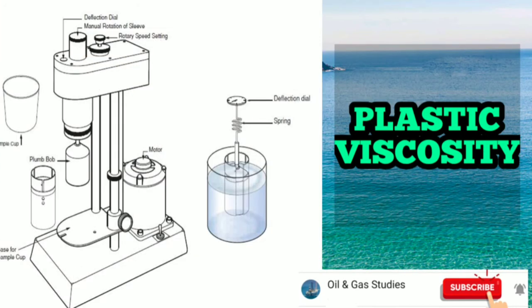Third is plastic viscosity, PV. Apparatus: viscometer or rheometer is a device used to measure the viscosity and yield point of mud. A sample of mud is placed in a slurry cup and rotation of a sleeve in the mud gives readings which can be mathematically converted into plastic viscosity and yield point. Multi-speed rheometers are recommended whenever possible since readings can be obtained at 600, 300, 200, 100, 6 and 3 rpm. PV, in cP, is measured by taking the difference between the dial readings taken at the two highest speeds of 600 rpm and 300 rpm.